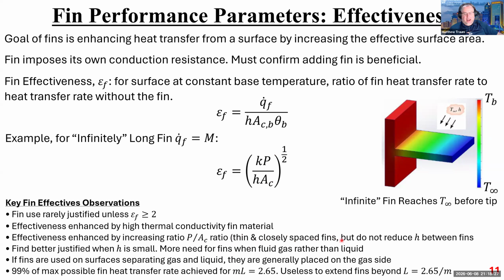It's actually fascinating. You can reach a point where the fins are so closely spaced to each other that you're actually messing with the forced convective heat transfer coefficient on the individual fins, because the fins are literally sitting in each other's wake or sitting in each other's boundary layers. And so the effective h is actually reduced, right? We just did this in quiz one, where the battery was sitting in the boundary layer of that thermal mat that it was sitting on, and h got reduced as a result. You all did quiz one. So you can put the fins so close to each other that they will actually interfere with each other's forced convection coefficient. So this works to a point until you start messing with the flow field.